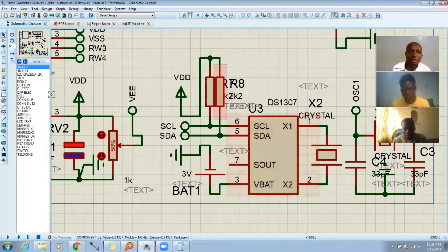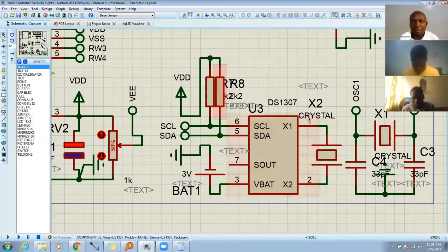Now, this is your power section. Quickly, I could explain what this power section is before we end this class. How does it work? You get a main step-down transformer that steps down 220 volts to 12 volts. That 12 volts is input into this terminal block. That voltage goes into a switch, this is a power switch.